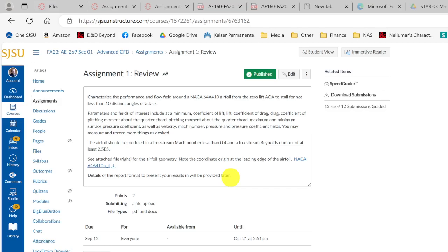The thing that threw me is that this is really not particularly characteristic of this airfoil. Like, it drops fairly rapidly, but not that rapidly. Like, you went from, in a matter of 2 degrees, right? Yeah. You went from 1.4 down to 0.4. You lost a full integer coefficient of lift, which would be the equivalent of this thing.